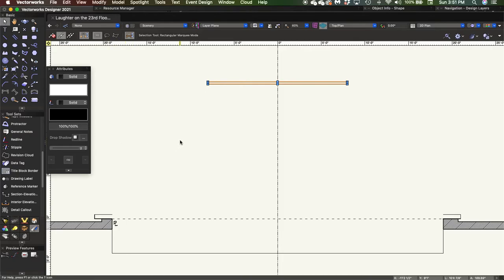So I'm going to create another wall, activating my rectangle tool again, and I'm going to go to the downstage right corner of this scenic wall that I just placed, get that smart point of bottom left. I'm going to click to start my rectangle and drag down into the left a little bit and enter into my floating display bar. And I'm going to make this one be -3 inches wide, and our delta y is going to be